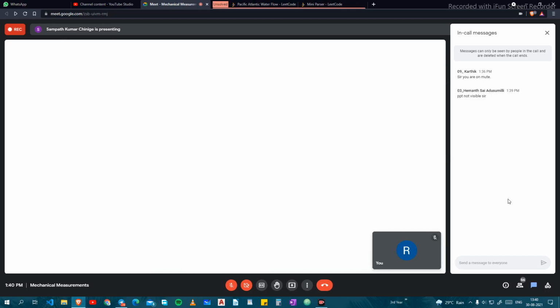Then we moved on to the unit step function given as an input for a first order system. We took the same differential equation, and we formed the output in the form of y equal to Ka plus (y naught minus Ka) into e power minus t by tau. Here we have a new term called tau, which is nothing but the time constant. And what it does, when we give a unit step function, because of the...